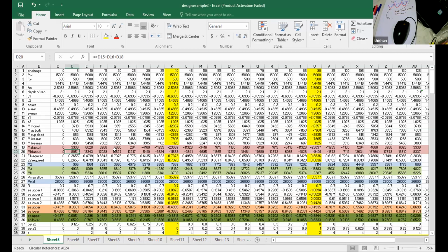When I'm calculating the minimum moment at a given section, I will use monolithic. That's how we do the calculations, because we cannot just say, like in a simply supported case, that we are not going to worry about concrete properties. You have to actually worry about concrete properties like creep and shrinkage. Those must be looked into. Why?